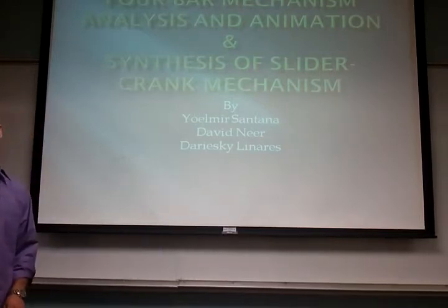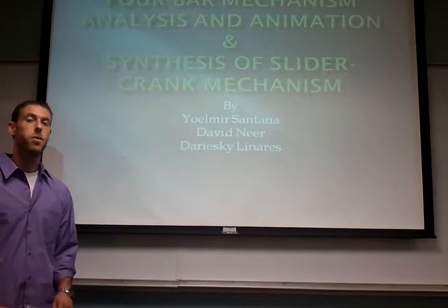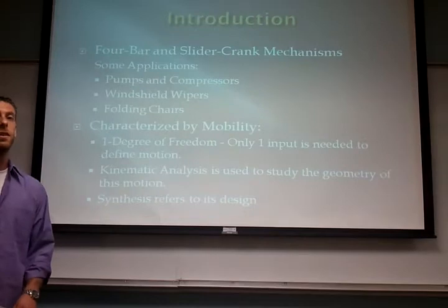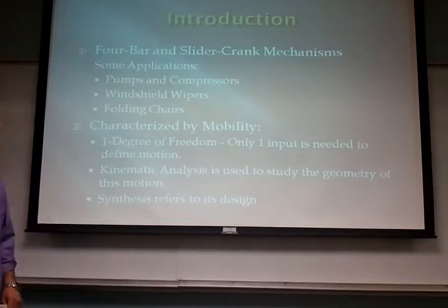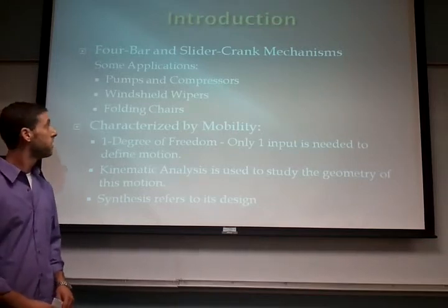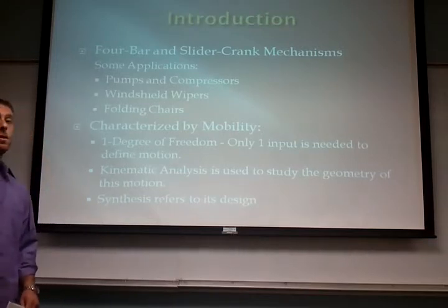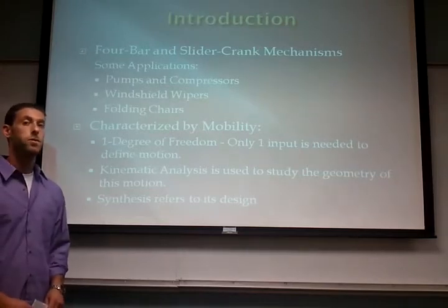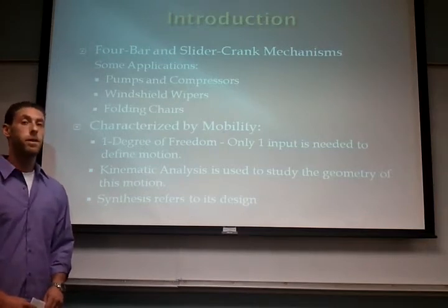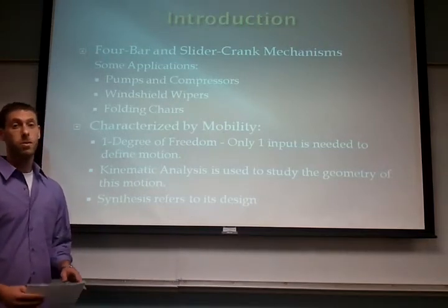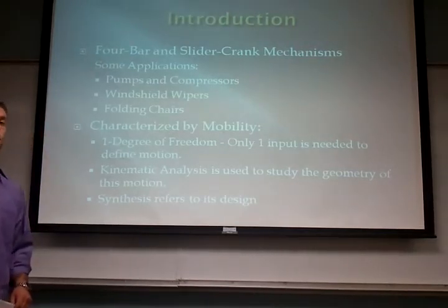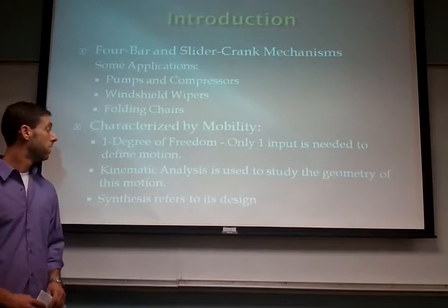The projects that we were working on were the analysis and synthesis of 4-bar and slider crank mechanisms. These mechanisms hold many applications in engineering usage. Some of them are pumps and compressors, windshield wipers, and then something as seemingly simple as folding chairs. In general, these mechanisms are in part categorized by their mobility, which for the slider crank and the 4-bar mechanism is equal to 1. This is also known as 1 degree of freedom mechanisms, which implies that only one input is needed in order to define the motion of the rest of the mechanism.